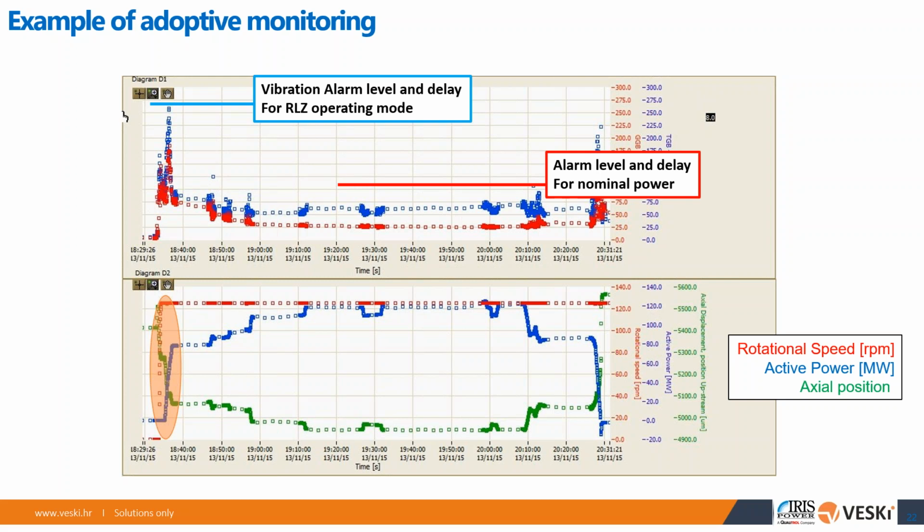This is how self-exciting vibrations occur. There is energy that cannot be absorbed or transferred, and then basically the easiest way is for the structure to start vibrating on its own frequency. This is what happens. But that own frequency here is the lowest. It's always the lowest frequency of the system. It's related to the whole structure, generator and brackets and turbine and everything. That's why it's so low.